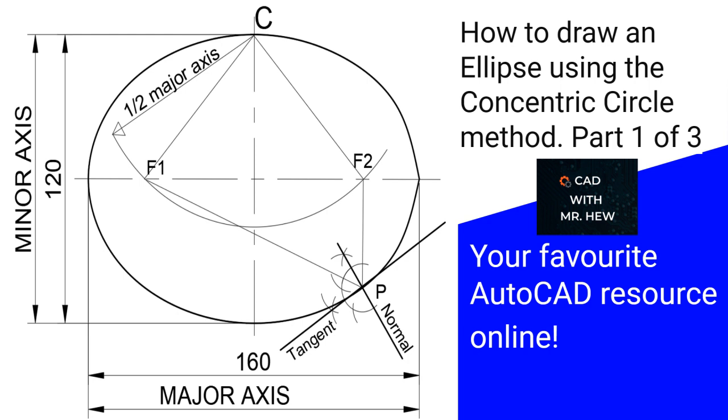Now, on the screen, we have the ellipse, which is a finished product. At the end of the video, you will be able to produce this ellipse, including the normal and the tangent. The two pieces of information you will need to draw today's ellipse are the major axis and the minor axis. For today's video, the major axis is 160 millimeters and the minor axis is 120 millimeters.